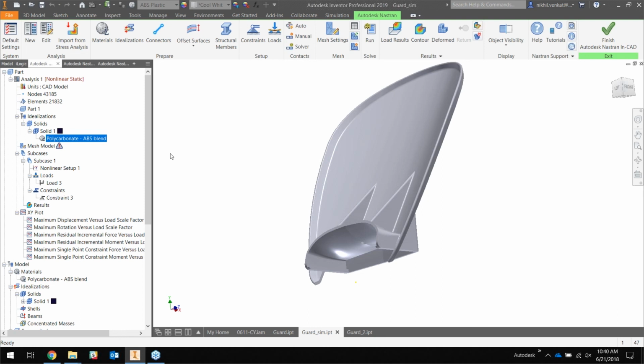There's another one from Steven here. I'm not sure if there was a quick answer for this, Nikhil, or if this will have to be for a convergence AVA. But how do you determine what part of the model is failing to converge? A quick tip: you'll know. When you're running the analysis, it actually shows you convergence of displacement, work, and load. So you'll actually see the one that's not converging. You'll be able to pretty clearly tell. If that portion is not converging, then make sure that the program ignores that as much as possible and just converges the ones that need to converge.